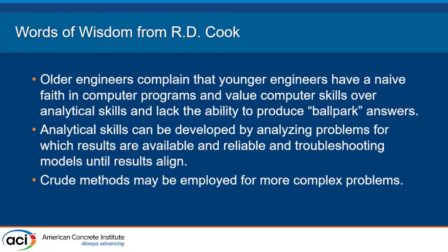I hear it a lot in our company sometimes. The older engineers like to go back in the day and they complain a lot that younger engineers sometimes just trust the model. So they'll run that model, it'll be a great, pretty picture, and they're just going to trust it. And when a seasoned practitioner looks at it, they say, well, this doesn't even make sense. What's my total static moment? Something's wrong. And then we go find the mistake. And that's really the sanity check piece. Do the results make sense?